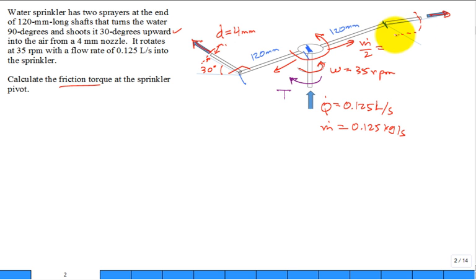And then it's going to come down, and it's going to cut where the torque is applied to the shaft, and then it's going to cut where the inflow is and come up and then come out like this. Does that make sense? So there's only going to be one torque applied to that control volume, and that's T. And you have one inlet mass flow rate down here coming in, and two exit mass flow rates at the tips out of that control volume.